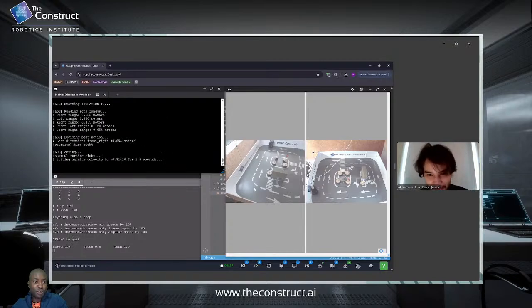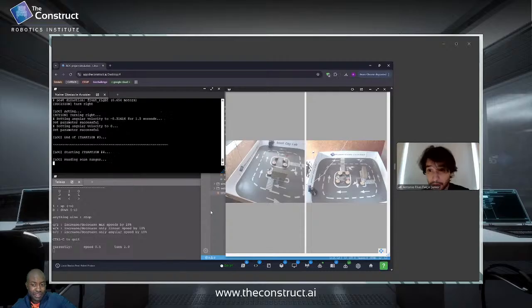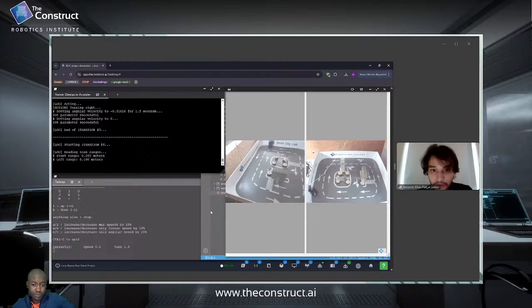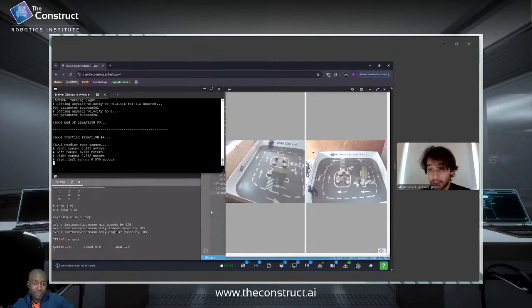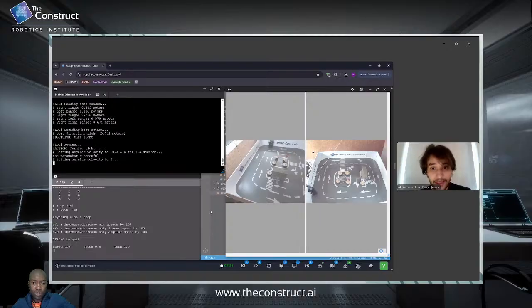Did you put any handling mechanisms for these kinds of cases? Yes, I've implemented some safety measures, mainly based on a logic of percentage. Basically, it detects how far the obstacle is in the best direction, the direction that's freer, further from the robot. You see that it managed to only rotate 25% of that distance, theoretically.